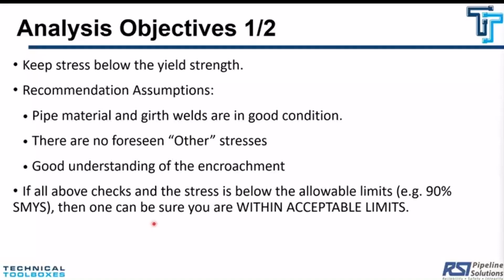For example, in the context of pipeline engineering, any type of activity within the right of way or near the right of way that can cause stress or pressure or vibration on a pipeline is called encroachment in general, right? Like, for example, a blast operation, because it can cause vibration and affect the pipeline, or pile driving operation, and so forth.